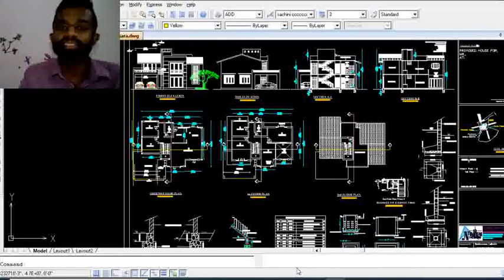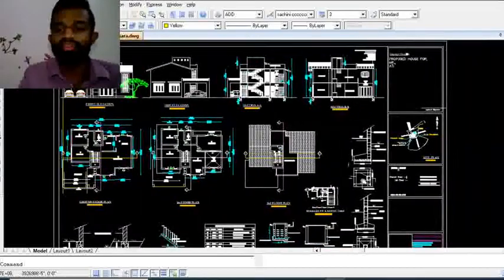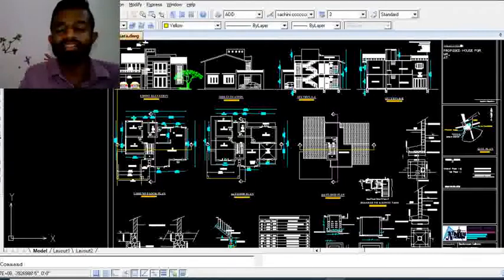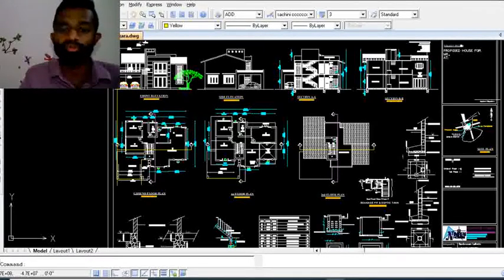So first of all, the structural engineer will come to your site and explore it, and he will find out the critical conditions of your land plot. He will find out about the boundary conditions, and he will check the existing buildings in your adjacent land plots, and if they have blind walls, you have to consider that, because if your building is also coming to the edge of the land plot, when you are excavating for your foundations, it will affect your neighbors' building foundations, and sometimes cracks can propagate in the already built buildings in your adjacent land plots.